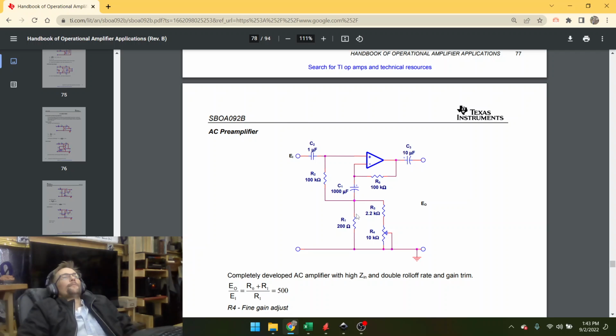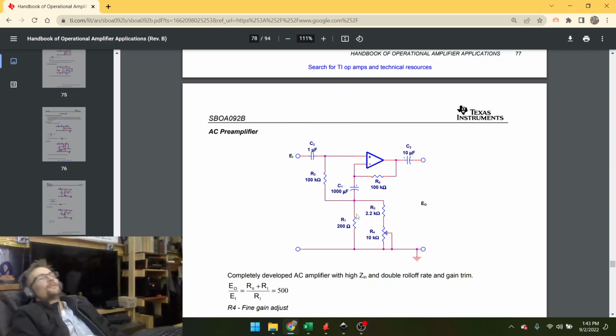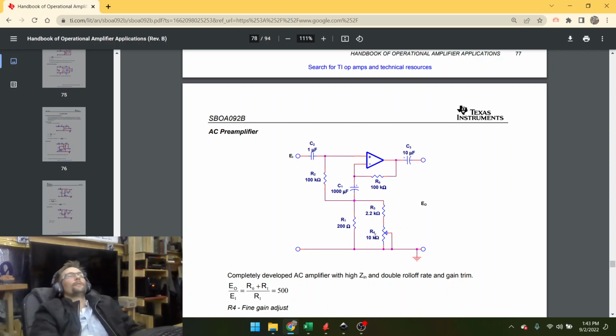So the bottom resistance there goes between 150 ohms to 190 ohms. So that potentiometer is a 10K, and it sweeps 10K, but the circuit that it's in, it only adjusts a couple tens of ohms.